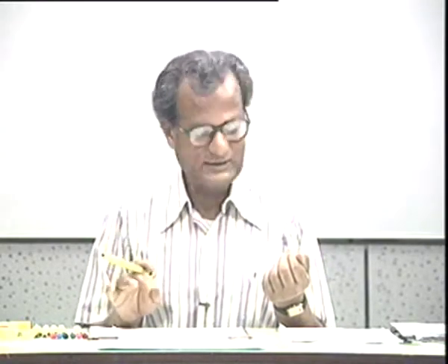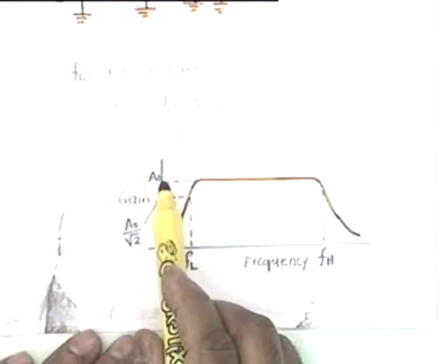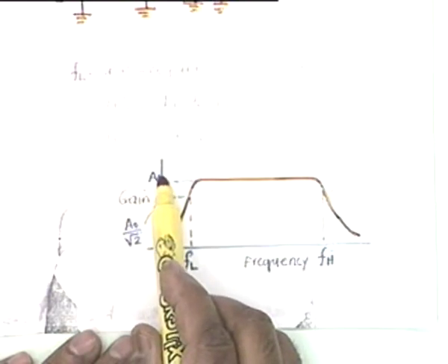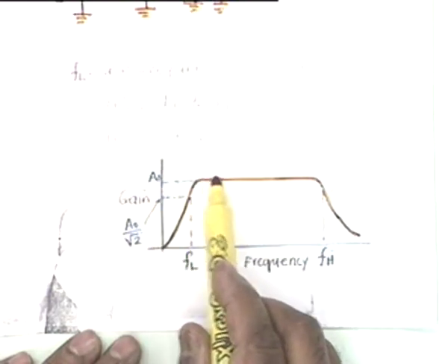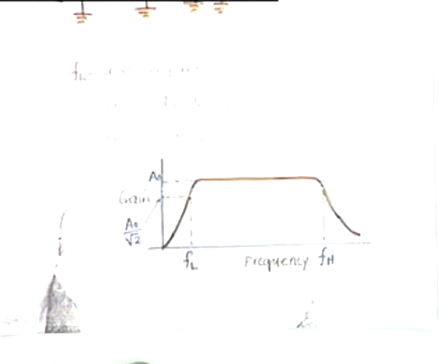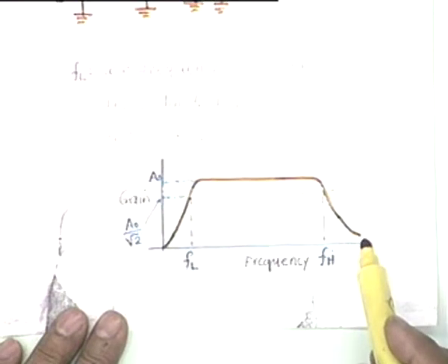As far as integrated circuits are concerned, as you know, we cannot use a capacitor. That's barred. We cannot make such a large capacitor, period. So what we do is we make coupling direct. Isn't that right? We make direct coupling, no capacitor, and therefore as far as IC amplifiers are concerned, they all start from DC. That is, the frequency response is that of a low pass filter. Is that correct? This is a band pass.